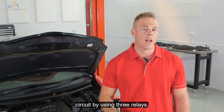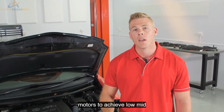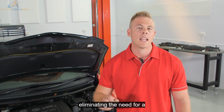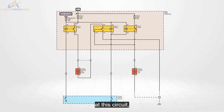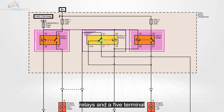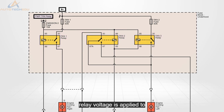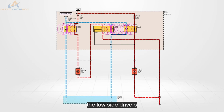By using 3 relays, we can now control dual motors to achieve low, mid and high speed operation, eliminating the need for a fan speed resistor. Looking at this circuit, we have 2 normally open relays and a 5-terminal, normally closed or changeover relay. Voltage is supplied to the relays via the battery and ignition feed. The circuit is complete when the ECM controls only one or a combination of the low side drivers.